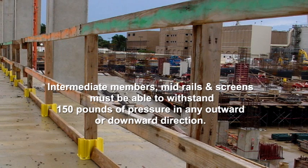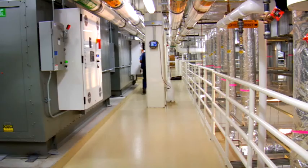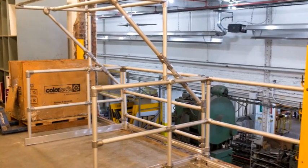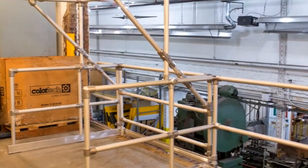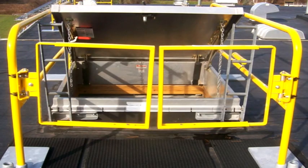Intermediate members, mid-rails, and screens must be able to withstand 150 pounds of pressure in any outward or downward direction. Intermediate vertical members must be installed no more than 19 inches apart. Guardrail surfaces must be smooth. Rails should not extend past a terminal post. Guardrails around access areas must have a self-closing gate that slides or swings away from the hole or the point of access and must be offset to prevent accidental walking into the hole. The gate should be in place at all times, except when the access area is being used.